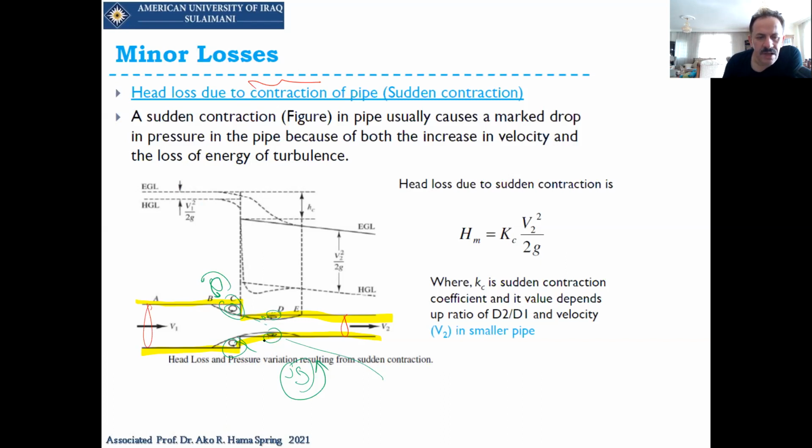So this will help make a kind of head losses. Now, this is the hydraulic gradient line. This is the energy gradient line. We say the energy gradient line is Z plus P over gamma plus V1 square over 2g, right? So this is at this point.